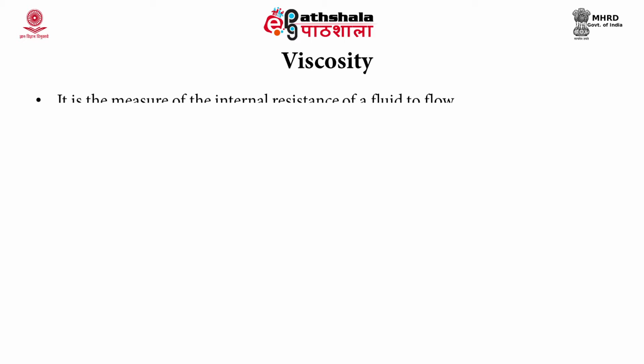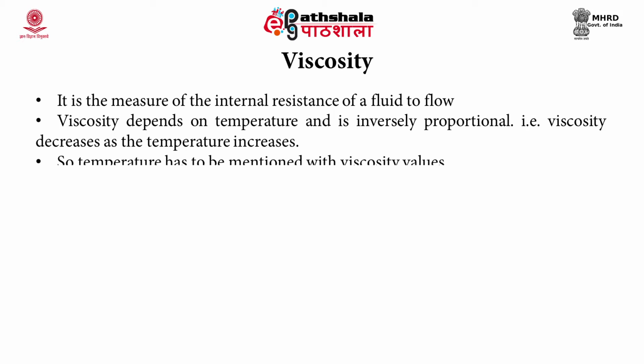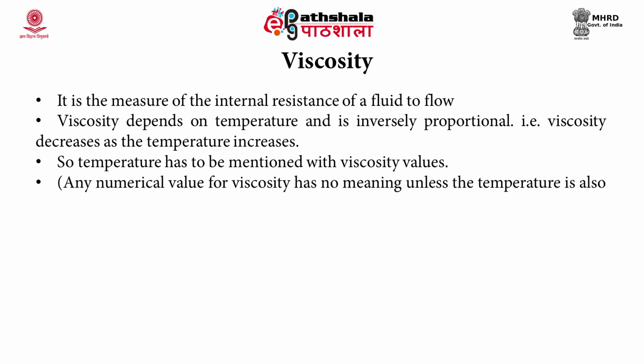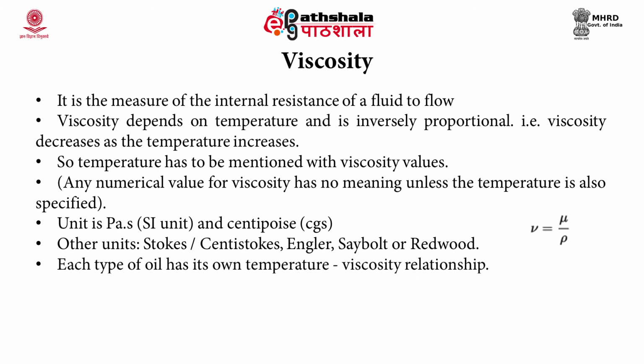It is the measure of the internal resistance of a fluid to flow, that is, the resistance offered by a fluid while flowing. It depends on the temperature, and temperature and viscosity are inversely proportional. That means viscosity decreases as the temperature increases. So, if we are mentioning any viscosity values, the temperature has to be mentioned, otherwise it has no meaning. The unit of viscosity is Pascal second in SI unit and centipoise in CGS unit.